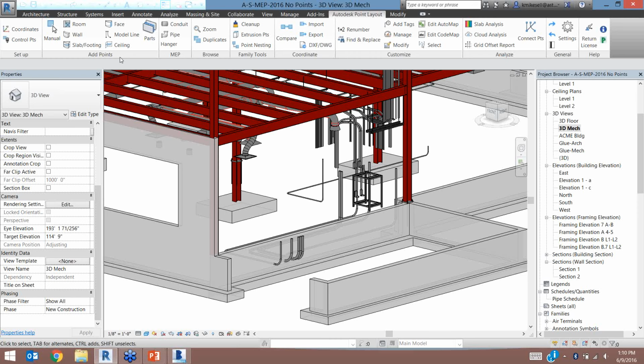You can, but you will generate duplicate point numbers. So if I copy the point in the point family, it will assume that that is the same point twice and number it the same in both positions. So you'll generate some errors by doing that. That's why it's better just to go ahead and create a new point.